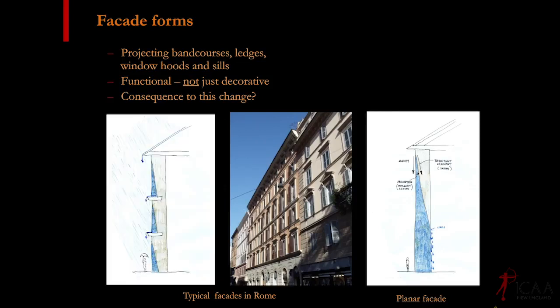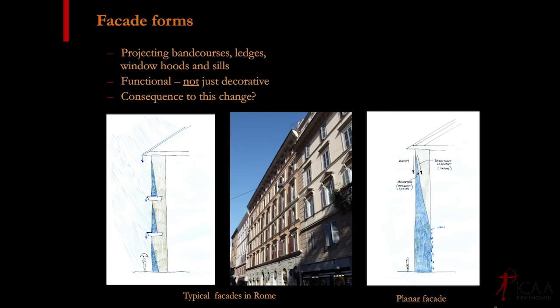Well, the way they work is these ledges and band courses are very functional, because they're basically acting like a through-wall flashing would today for us in a cavity wall. Structurally, these band courses, which might be something like travertine, want to project deep into the wall to be structurally stable as they stick out. These are not just glued-on ornamental details. And with just a very slight wash slope to the outside, these essentially act like flashings. They're basically resetting the clock at every floor line. So instead of having this gradient of water get to the inside and cause all these problems, it gets the water out at every floor and manages it on the way down.